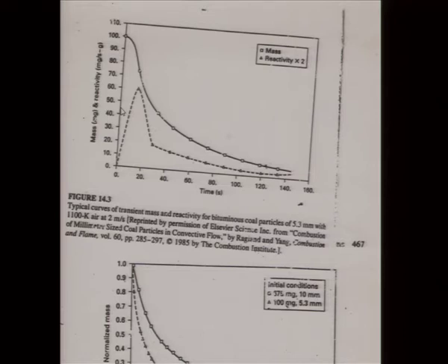So what is the reason behind this? If you are working in a power plant and the coal has 20% volatile matter by virtue of proximate analysis, in actual boiler combustion, it may give you much more volatile matter than that 20%.